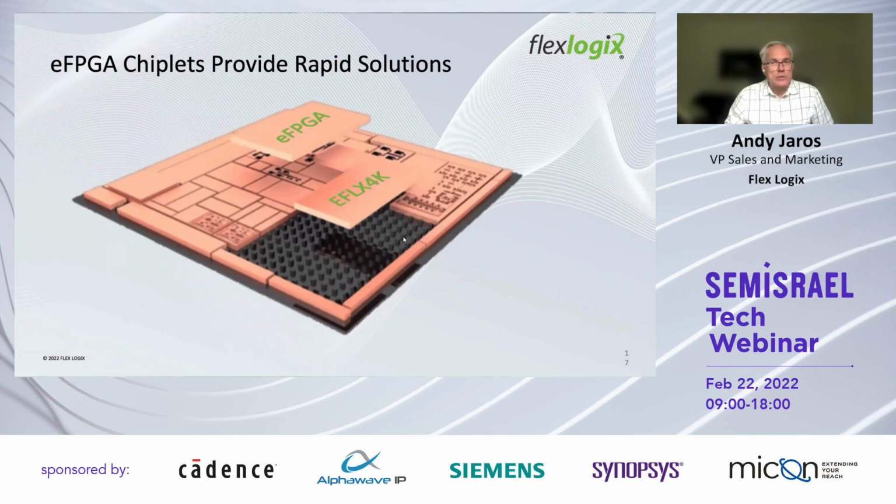One of the more recent trends taking place in the market is companies exploring a chiplet approach to increasing processing power and flexibility to support customized semiconductor solutions without having to tape out an ASIC for each end customer. Using embedded FPGA to make an FPGA chiplet provides the extension of this chiplet ecosystem and avoids the reliance on securing known good die from FPGA companies, and puts you in control of the supply chain in developing your own chips and managing your chiplet ecosystem.